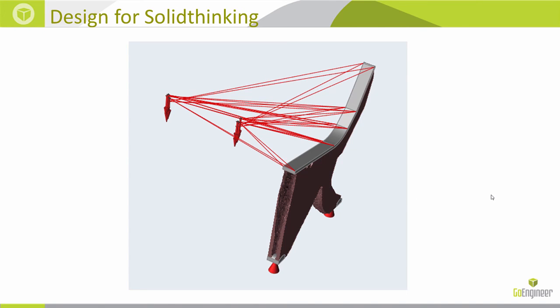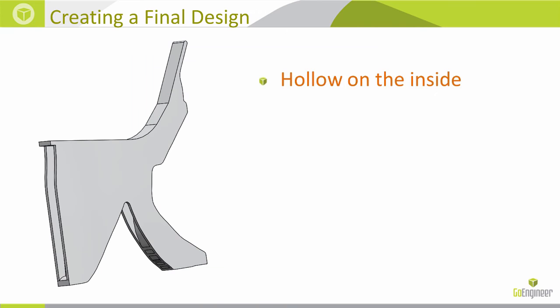So what are some of the changes that we saw? We saw that based on the optimized geometry, the insides were now hollow, and it's about 20% lighter than the original design. And also we validated this using finite element analysis.